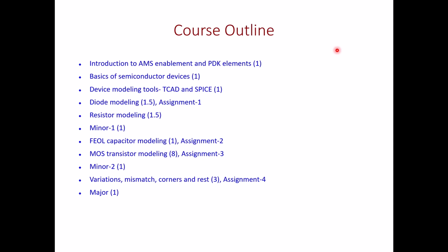The focus in this course is typically on industry standard models, the models which were standardized by CMC. So the MOSFET models we cover typically include industry standard models. We start with something like BSIM3v3, and then we often talk about BSIM SOI. Currently we are looking at BSIM-BULK and BSIM-CMG, so all kinds of advanced MOSFET models are discussed in this course. For the other passive device models or other active device models such as diode models, we try to talk about standard models.